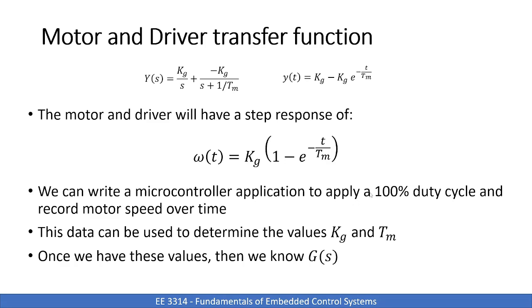So if we want to simulate this response in the microcontroller, we want to basically look at the step response of that. Okay, and that's what we did for the motor modeling assignment. We recorded the step response of the actual physical motor, and that can be used to determine these two parameters that describe our driver and motor system, right? So you should be kind of working on that right now. Once we have these values, then we know our motor and driver transfer function G of s.